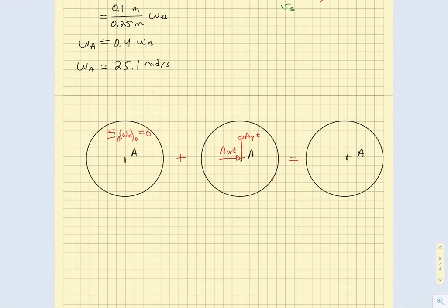And since we're talking about a discrete time interval of t, we look at the reaction forces at A. So you have A_Y multiplied by the time t, and we have A_X multiplied by the time t. Those are the two forces acting for the pin connection. And then we have the force that comes from the moment on the small motor. Remember, the small motor is going in the counterclockwise direction. That means at the point of contact, which we call point C, there's going to be a force, and it is just the force multiplied by the time that it takes.